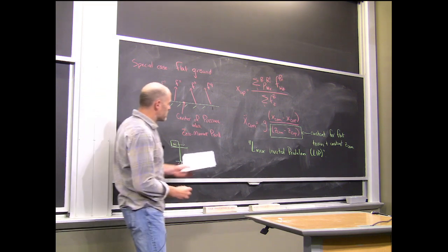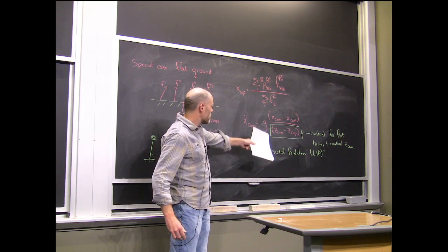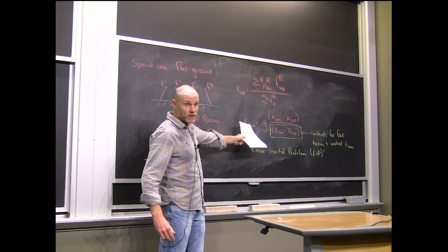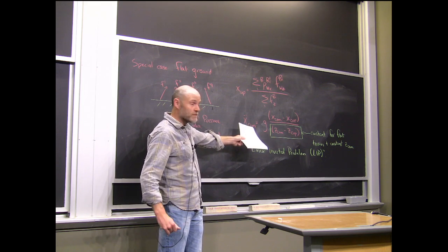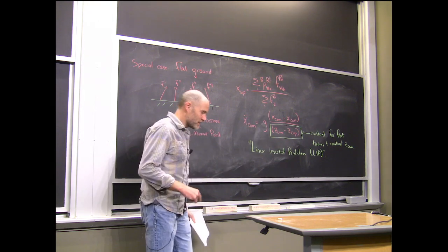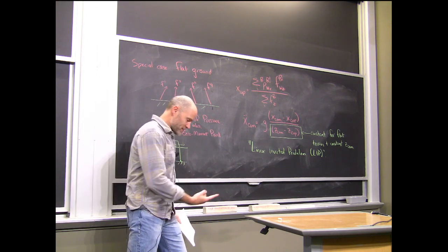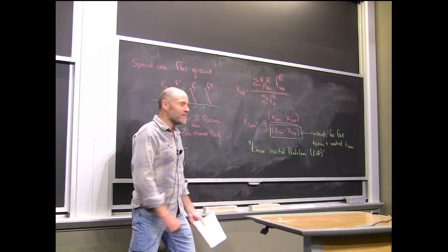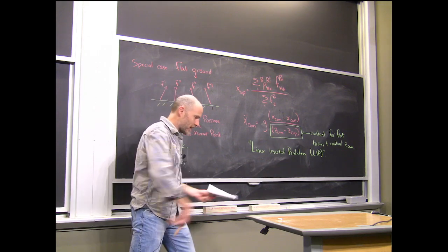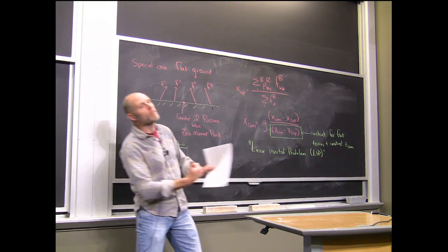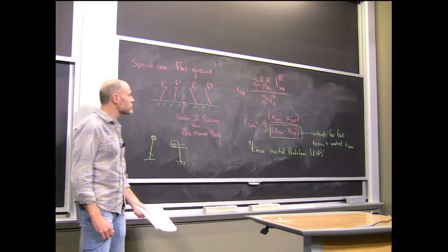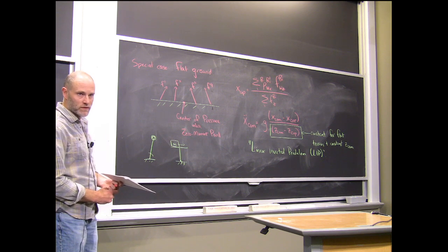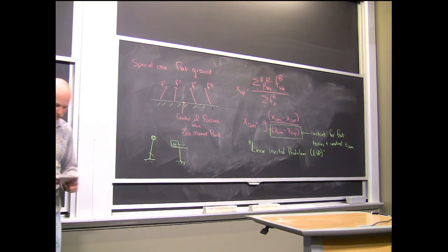For those of you trying to find these kinds of connections, one of the things that's interesting about this is that it is non-minimum phase dynamics. It's an interesting linear system in the sense that in order to make my center of mass accelerate this way, sometimes I have to go the other way first. I have to move my center of pressure in the opposite direction in order to start accelerating, and then go back the way I was really intending. But as long as your airplane does that too, I would be willing to concede the point.